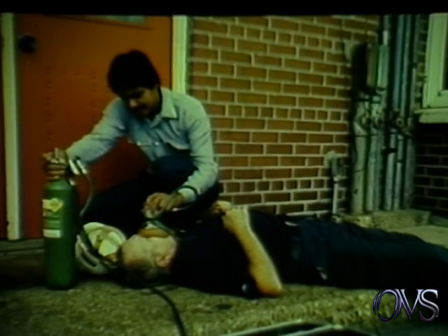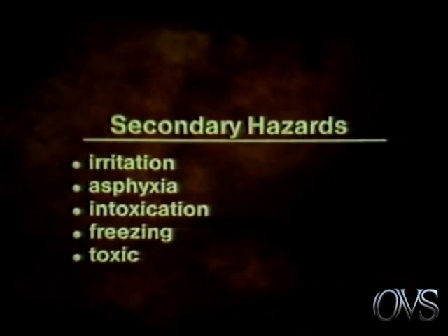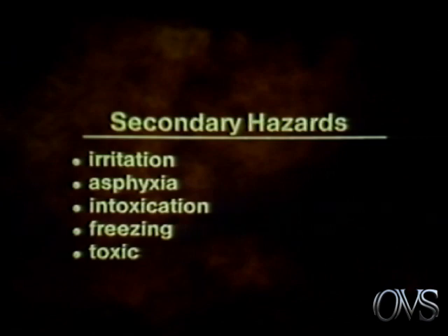In summary, the biggest hazard to persons in Amoco Pipeline is the ever-present danger of fire and explosion. Secondary hazards are the physical effects of exposure to the liquids and gases we pump: eye and skin irritation, the possibility of asphyxia or intoxication in vapor-rich atmospheres, freezing effects from liquefied compressed gases, and certain toxic effects, notably from benzene and xylene.